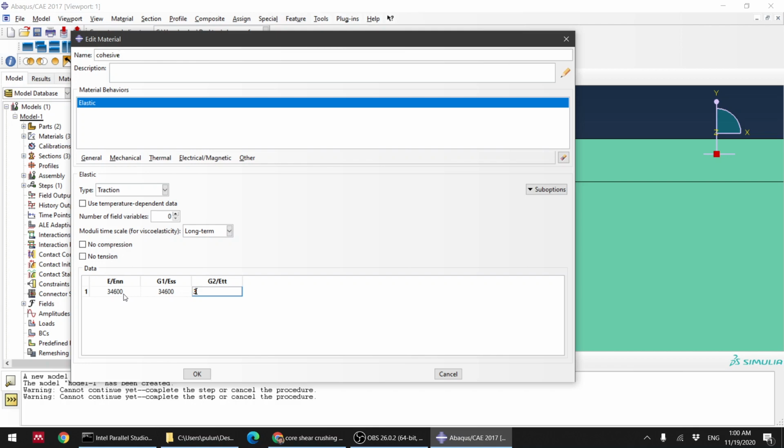When the delamination hasn't started yet, the cohesive element should not give additional compliance or additional stiffness to the problem. If you read papers, they will call it the spurious compliance problem. So to remove that problem, we need to put something that is so stiff to ensure continuity between the skin and the core. Yeah, I don't know what I'm talking about.